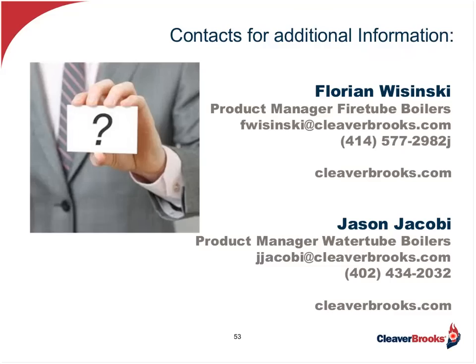No, they're not. As a matter of fact, that's an ideal level. And the reason that we manufacturers, and that's not just us, it's all of our competitors as well, will recommend 3% O2 is because if you start getting close to stoichiometric with zero excess air, you start to get into some real problems because you don't have any control over the ambient temperature, the relative humidity, the barometric pressure and the calorific value of the fuel. And all of these can put you into a very unsafe condition. So we set these burners to operate at 3% O2 or 15% excess air for that reason.